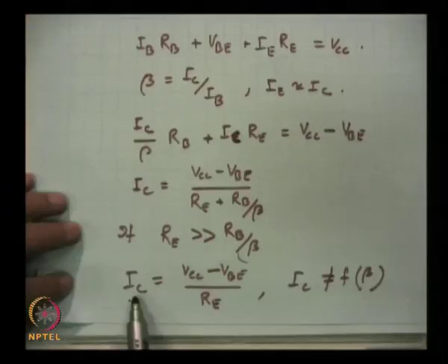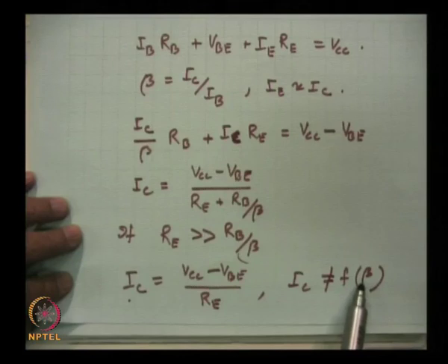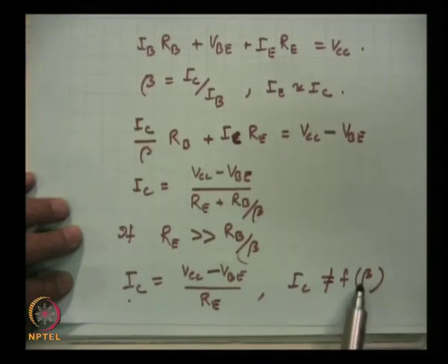Continue our discussion on biasing of transistor. We were talking about the self bias, in which we have shown that the collector current was independent of the changes in beta, and as I said earlier, a circuit which shows stability against one kind of variation will take care of variations due to other reasons. That means the cause of variation is immaterial.